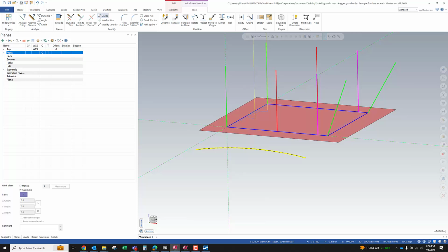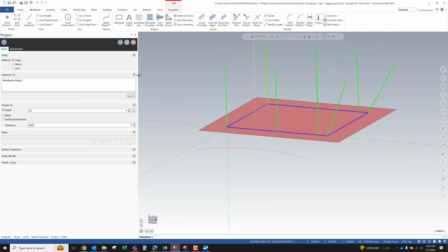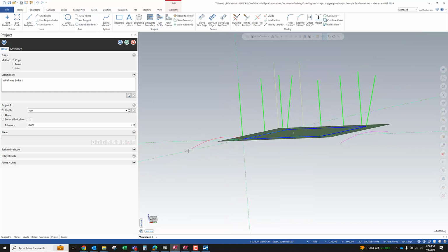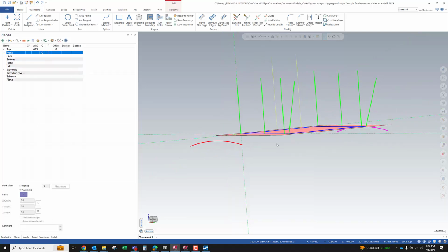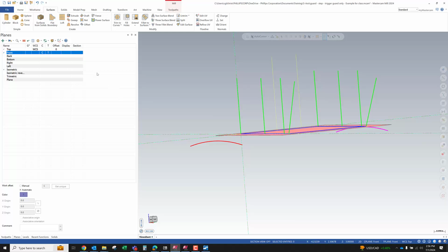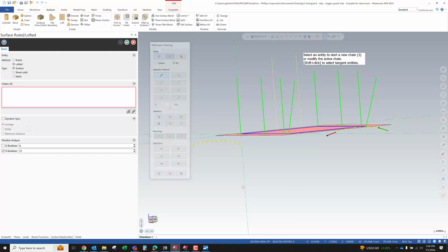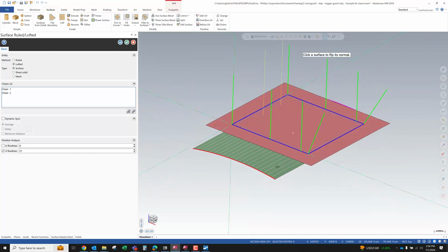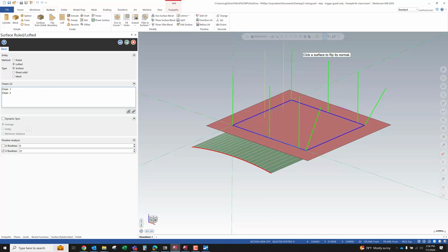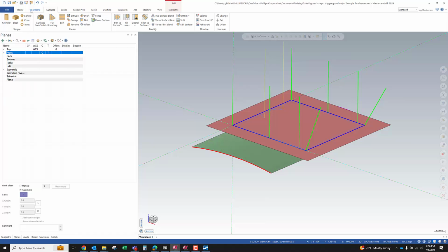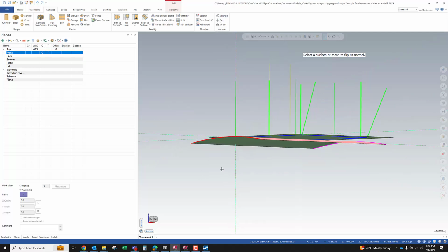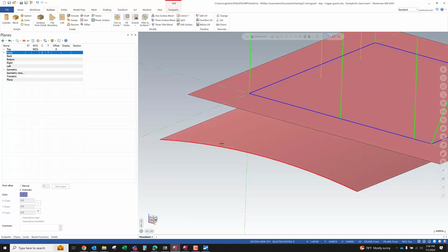Take that arc and I'm going to project it. I'm going to copy it to, say, -6. Let's make sure that's far enough. It is. Great. I'm going to go to surfaces, and I'm going to loft a surface, and I'm going to use those 2 chains. And we get a surface. I'll say OK, and I want it reversed, so I'm going to go to change the normal, and I'll click on it. By the way, how can I tell what side of surface is the normal?